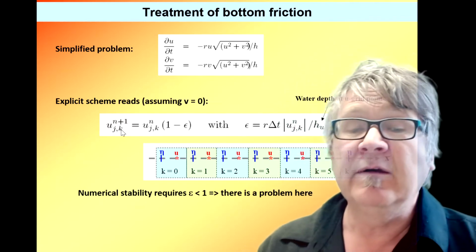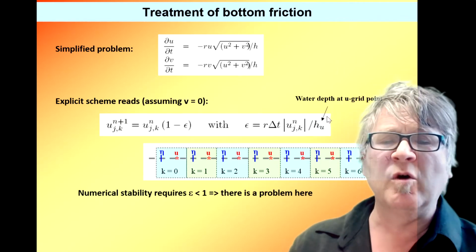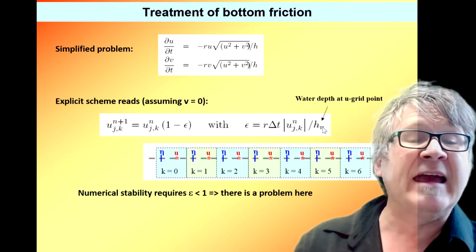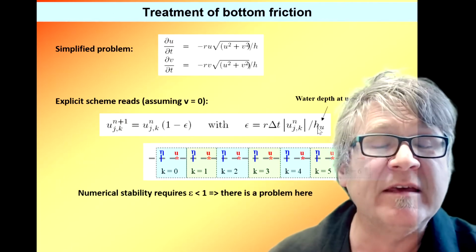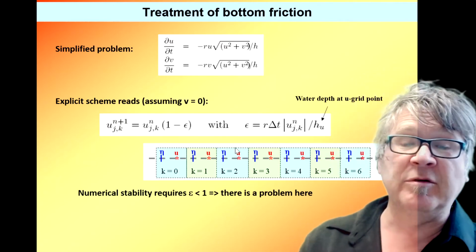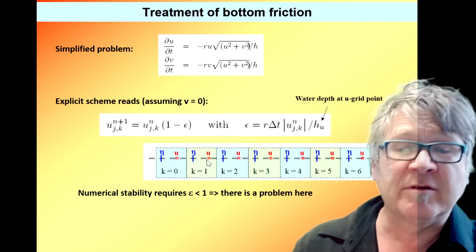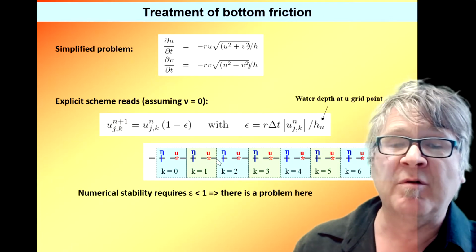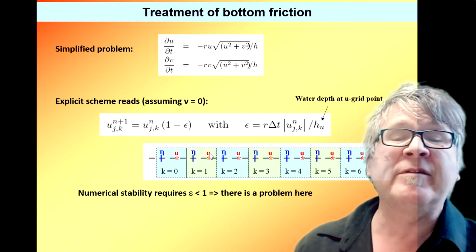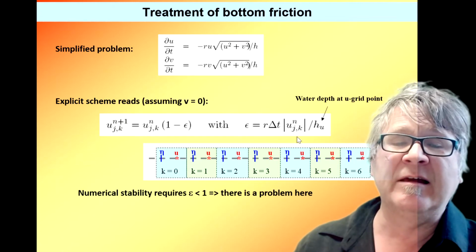All right. And then you have to be a little bit careful here, but you have to work out that I use the writing HU here because the H value has to be interpolated on the U velocity. So this is how the grid looks like in one dimension. You predict at U, and the water depth or sea level points are to the left and to the right, and you actually have to take the sum and divide by 2, and then you have it interpolated. So this is just a little detail.